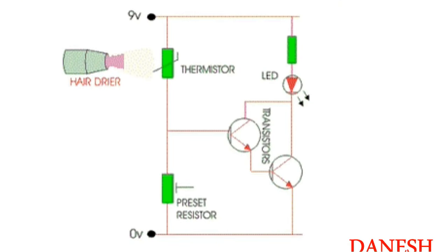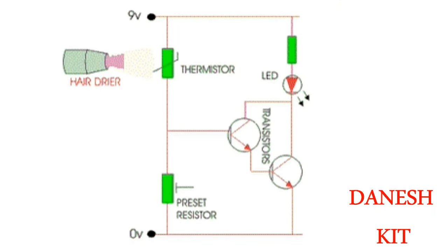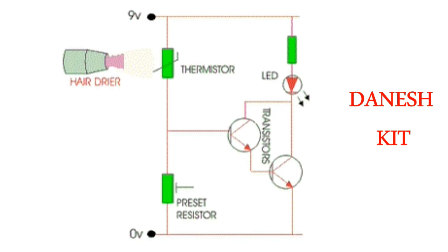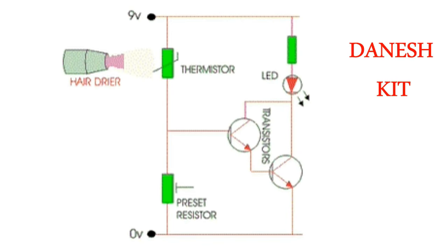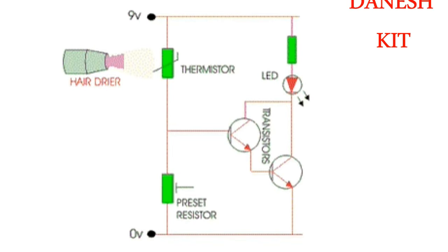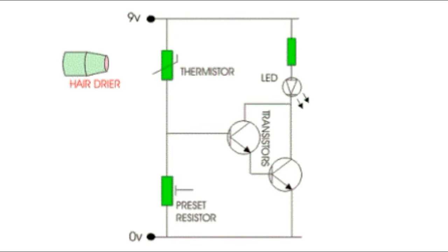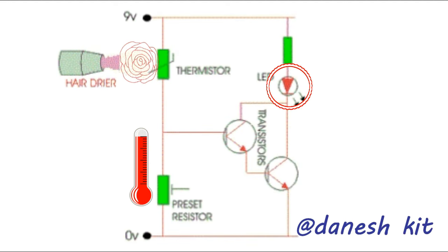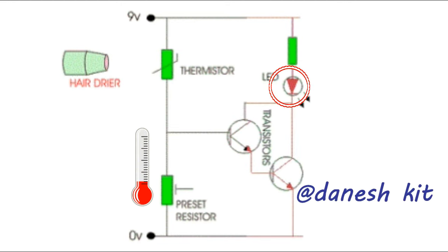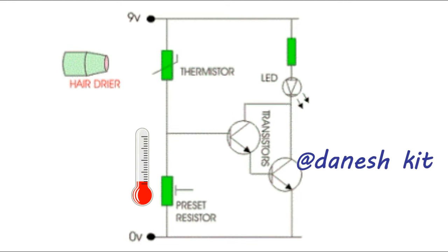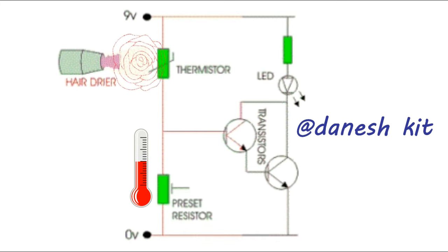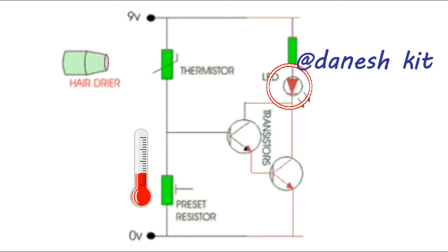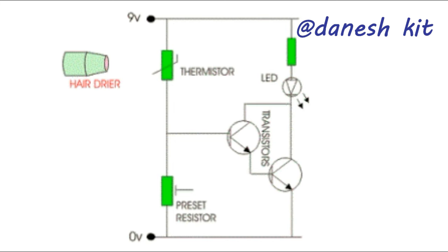A simplified circuit is shown. When the thermistor is cool or cold, the LED should not light because of the high resistance. However, warm up the thermistor by blowing warm air from a hairdryer across it. This should warm it sufficiently that in a few seconds the resistance will drop and the LED will light. The preset resistor can be turned up or down to increase or decrease resistance. In this way it can make the circuit more or less sensitive.